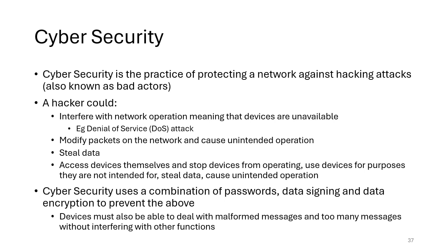Now Modbus TCP doesn't have any security on it, so you could potentially turn a PLC off, or put it from automatic into manual mode, or write directly to I/O if you had access to that level of the network. So modifying packets on the network and causing unintended operation, that's pretty serious. But having said that, most of the time you would be blocking those ports. To stop Modbus traffic on your network, you just block port 502, and that's it. You fix that problem. So the firewall resolves that issue very quickly.